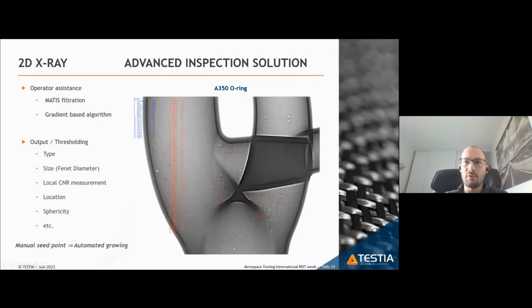I mean, if your first set of results are not perfect, for example, on this part, it's on a ring image with our system. So you have some indication which are not defect, and so the operator can directly threshold the result on specific value of the output, or make a selection on the image to approve or cancel indication. And so like here, we can select, okay, this area was not containing defect,